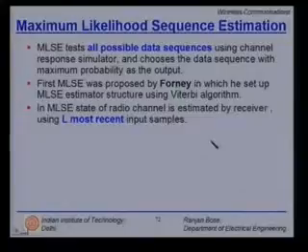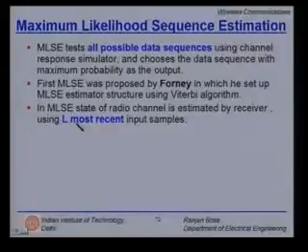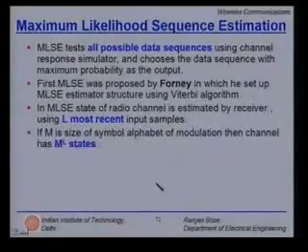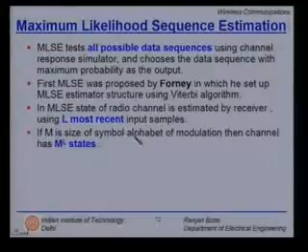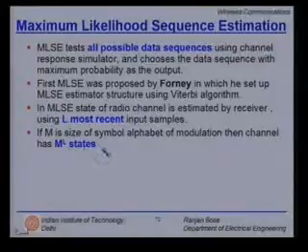The MLSE state of the radio channel is estimated by the receiver using L most recent input samples. If m is the size of the input alphabet of modulation, then the channel has m raised to L states.